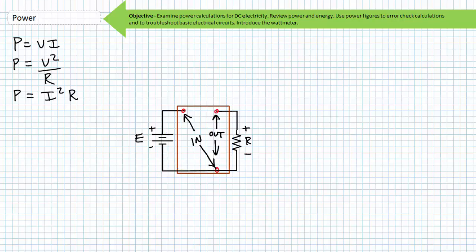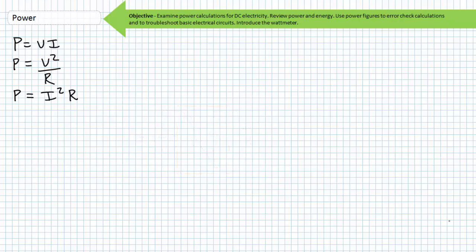Be aware you might run across 3-terminal wattmeters where the bottom terminal serves as a common terminal to the input and output pairs. Again, consider the placement of those meters inside that wattmeter. Voltage is measured across. Current is measured through something. The wattmeter kind of just serves as a single bridge between our input and output if our only measurement concern is wattage. Let's bring this discussion of electrical power back full circle.